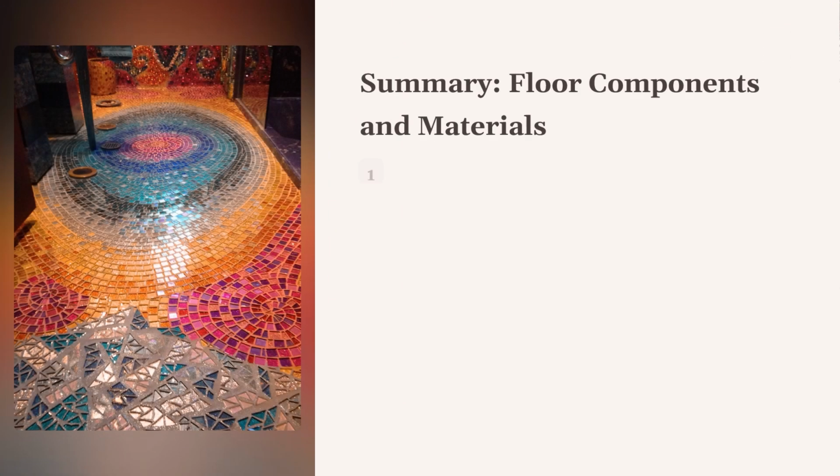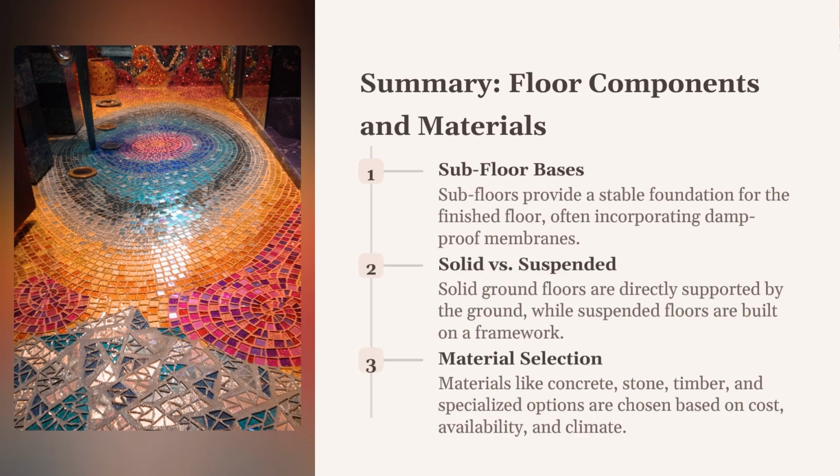Techniques like damp-proof membranes and effective insulation are essential to mitigate these issues. We explored the components of floors, including the subfloor base, which provides structural support and damp resistance for ground floors. We also differentiated solid ground floors resting directly on the ground from suspended floors elevated above the ground level.